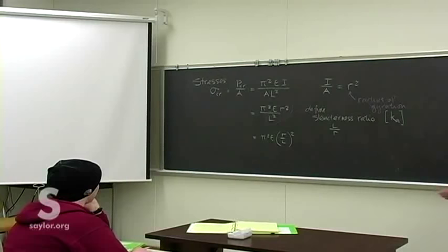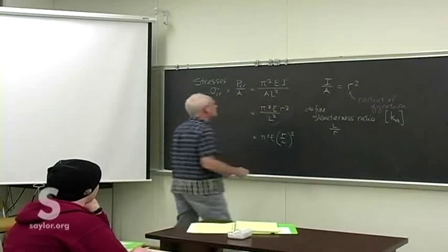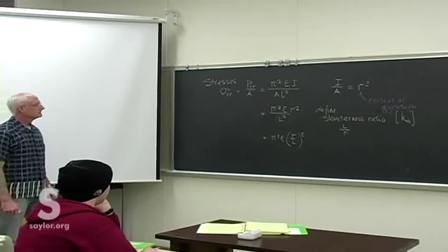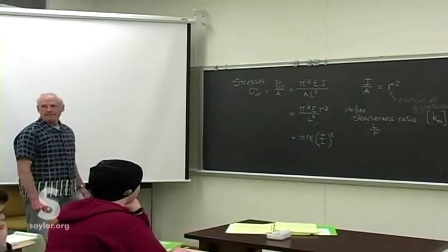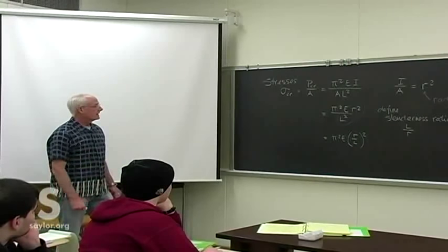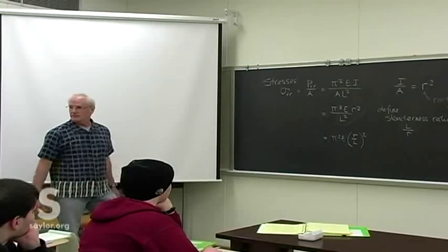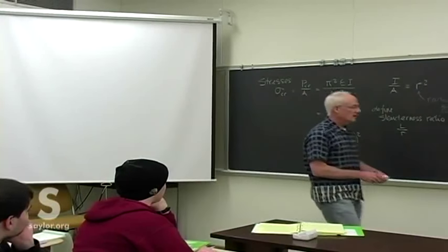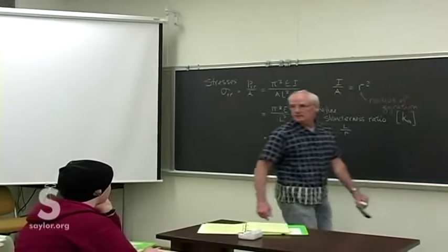Is that area just an area? Yeah, the cross-sectional area. Didn't in dynamics we define it as mass times distance over a moment? This is area, first moment of area that we're using, not necessarily first moment of mass like we use in dynamics.